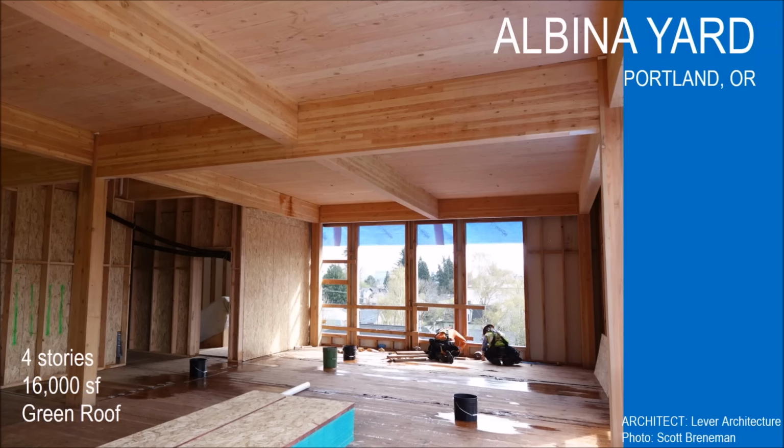So here's the Albina Yard project, and this is a classic example, if you will, of a modern post and beam project. In that, we see a glulam grid supporting the floor. In this case, we have beams and girders running in two different directions, and those are supported upon glulam columns. But then spanning between the beams of the floor framing system is our CLT panel.